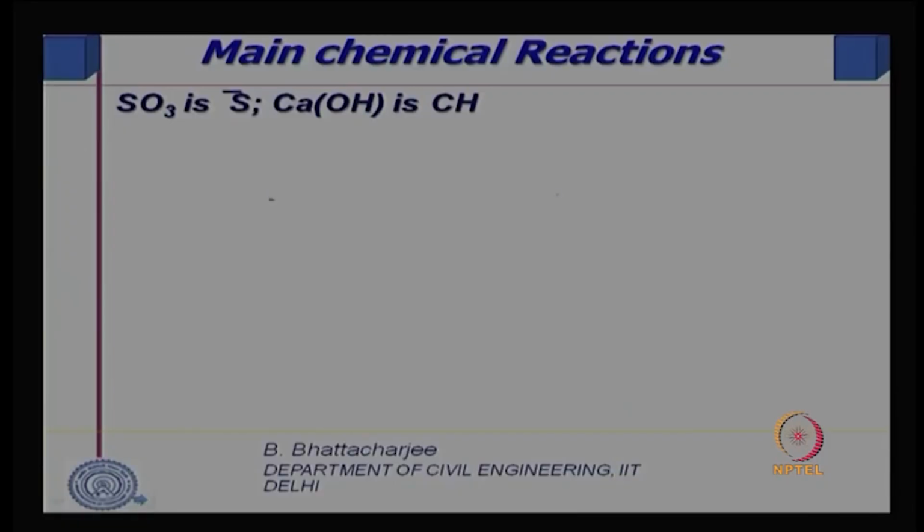The next important chemical reaction is of course C3A reacting with 6 water, forming calcium aluminate hydrate, C3AH6. This is the typical reaction.